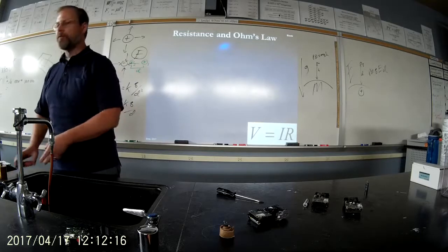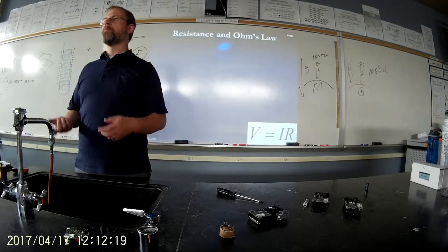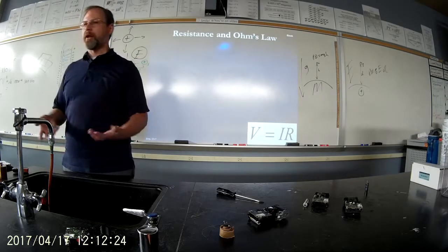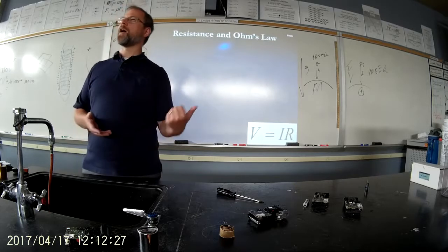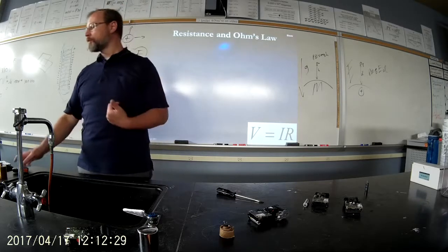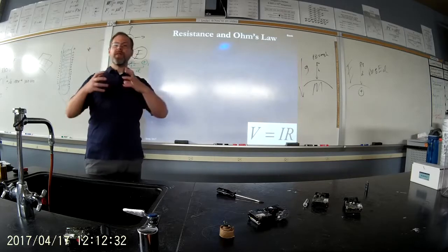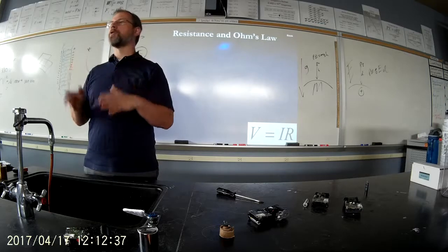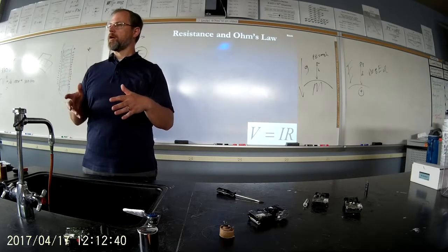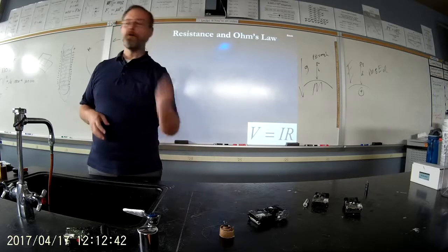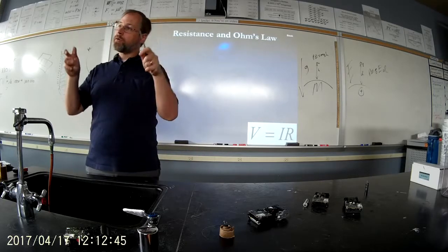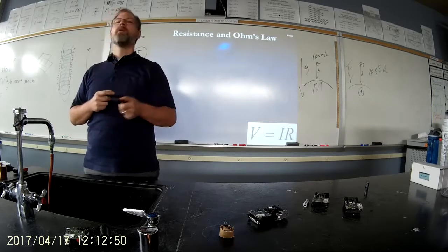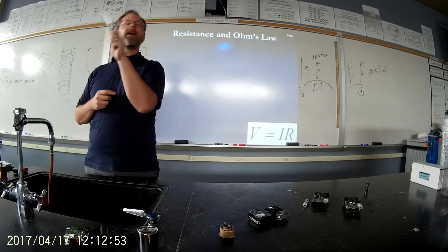Well, that is Ohm's law as much as F equals ma is Newton's second law. Newton never wrote down F equals ma. Similarly, Ohm's law is not really V equals IR, that's just a great formula. What Ohm's law really states is that something that obeys Ohm's law has the same resistance regardless of what voltage you apply to it. In other words, this screwdriver will probably be ohmic if I apply 1 volt to it, 10 volts to it, 1,000 volts to it. But if I try to apply 100,000 volts to this, it's not going to be ohmic anymore.